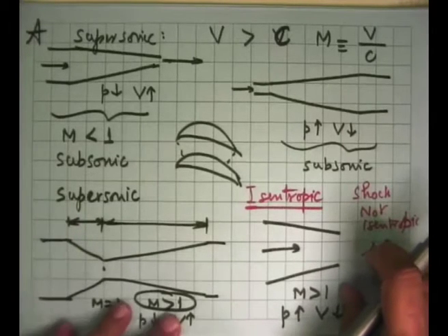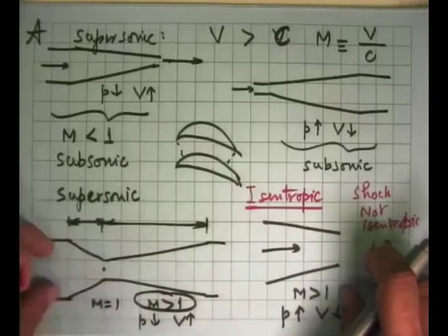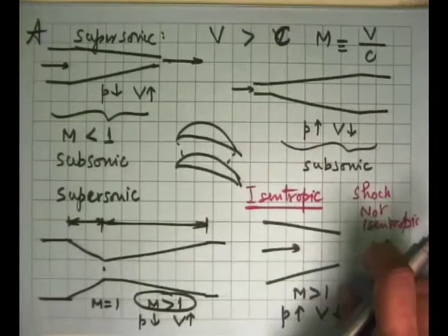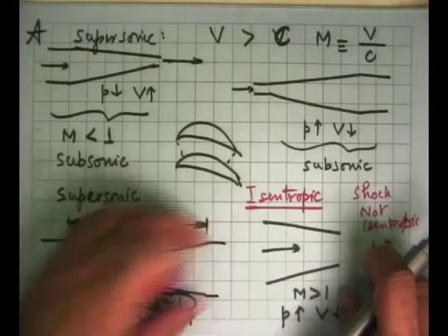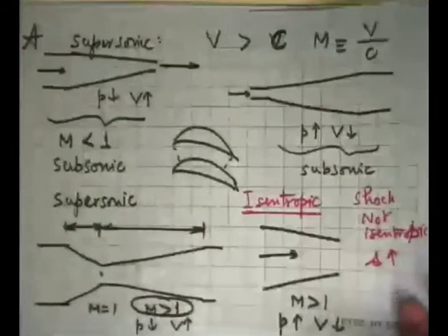But from our perspective, what we have learned in thermodynamics is fine. We could say that there is a nozzle and expand it to a pressure where the Mach number actually becomes more than 1. But thermodynamics does not tell us what the shape has to be; we have to get that from compressible flow theory. So that's the thing about supersonic flow in a nozzle and a diffuser.